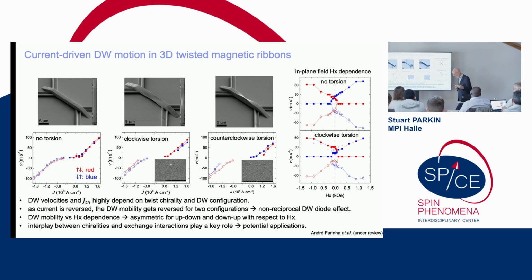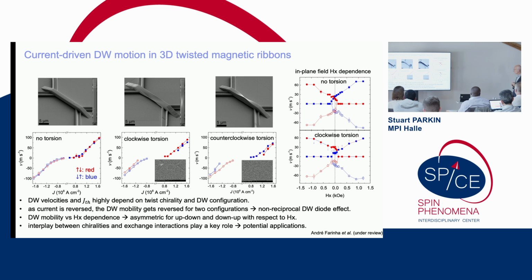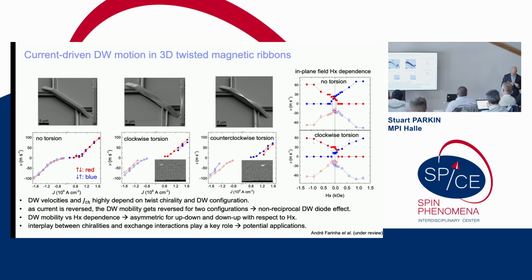Now we can actually atomic layer deposit the cobalt-nickel layers, a few angstroms. Normally in ALD, we're talking about 10 nanometer thick layers. So this is the first time this has been demonstrated, to our knowledge. Once we've done this, we can really create this three-dimensional racetrack on vertical walls. This is our goal. We expect to achieve that shortly.